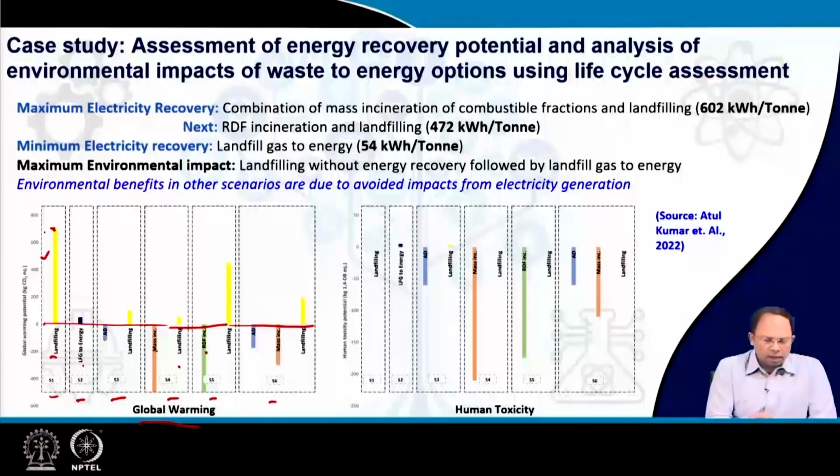that is being generated. Whereas, for the other processes, like anaerobic digestion, it doesn't generate gas, but because of it, I am creating energy which through indirect emission would have generated energy. So, everything that you see below, these are in minus or negative terms. That means these are avoided emissions that have been possible because we are doing RDF or incineration and so on. So, when I take the overall thing, we can say which process is better in regards to the global warming potential.